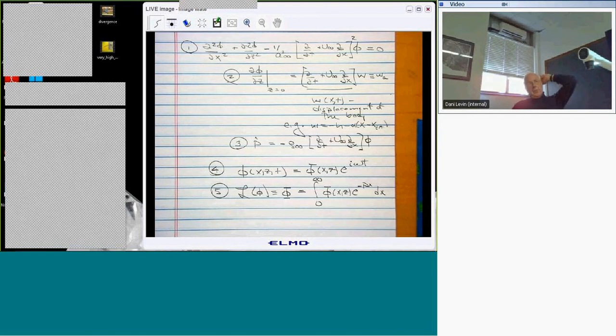If you've had some Laplace transform theory before, you know usually you're doing it with respect to time, but in this case, we can do it in supersonic flow with respect to x because nothing's happening for x less than 0. So x basically behaves in a mathematical way like a time variable. It's physically a position variable, right? But it has all the same mathematical properties in supersonic flow of a time variable.